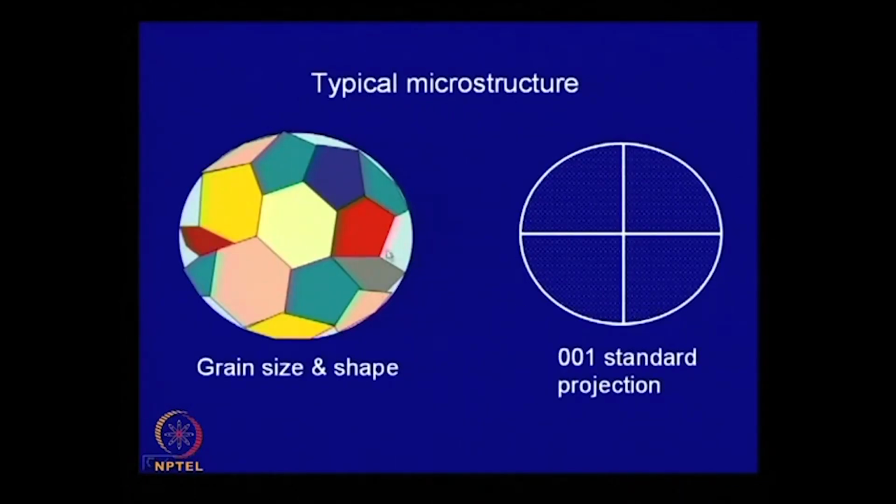Now, this picture shows that some nucleus has formed, but this is a concurrent process. Nucleation and growth both take place simultaneously, and the nuclei will keep growing, and finally, when each grain meets another grain, growth in this direction is inhibited. Finally, you will get a number of grains, and each grain may have a different orientation, shown by a different color, and this is a typical microstructure of a solid pure metal.